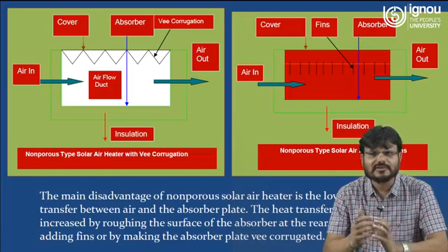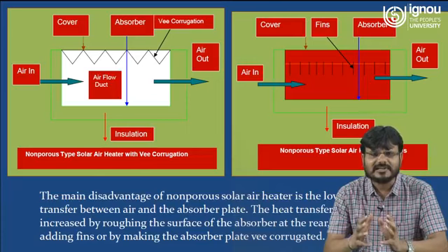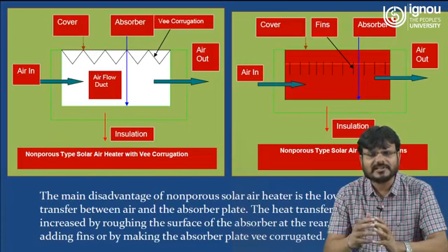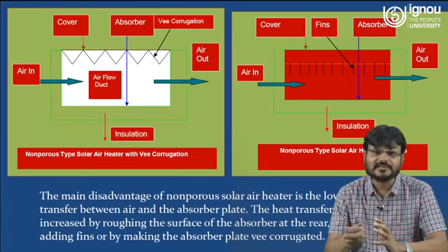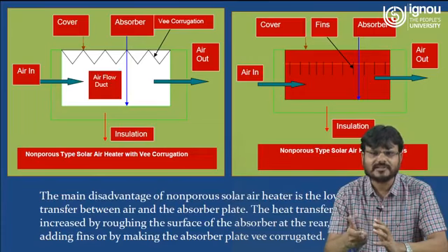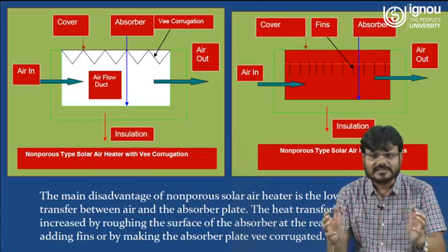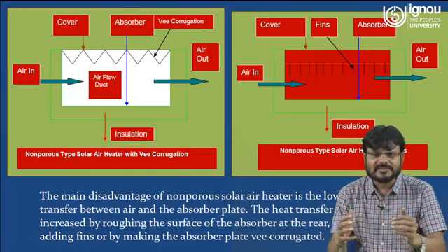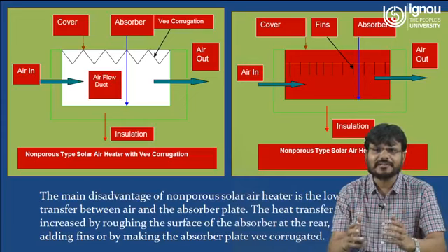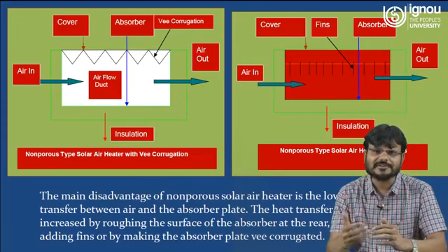So if you are using a number of fins in the air chamber, that means you are able to increase the collector area. If you are able to increase the collector area, that means heat associated at the collector is more, that means you are getting more thermal energy, and this associated thermal energy will transfer to the working fluid, that is air, and this hot air is coming at the outlet point. So you are getting more heated air. That means the difference in temperature is more. If the difference in temperature between air in and air out is more, that means more thermal energy you are getting.